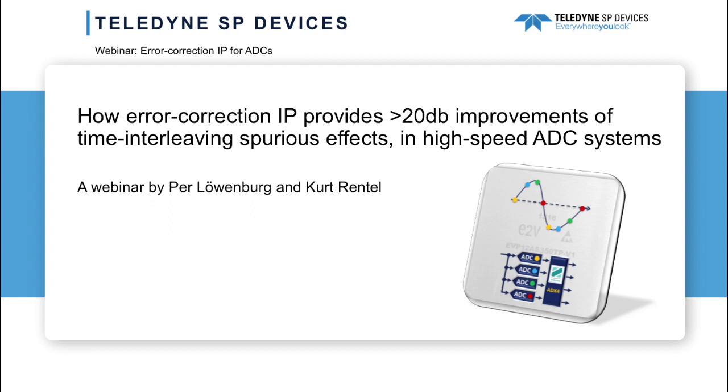Welcome to this webinar with the title How Error Correction IP Provides More than 20 dB Improvements of Time-Interleaving Spurious Effects in High-Speed ADC Systems. In this webinar, we will highlight the possibilities of digital error correction in gigasamples per second analog to digital converters. We will share some insights in so-called time-interleaved ADCs and illustrate the effect of mismatch and mismatch error correction. We will further demonstrate mismatch error correction using the commercially available Teledyne SP Devices IP core ADX.